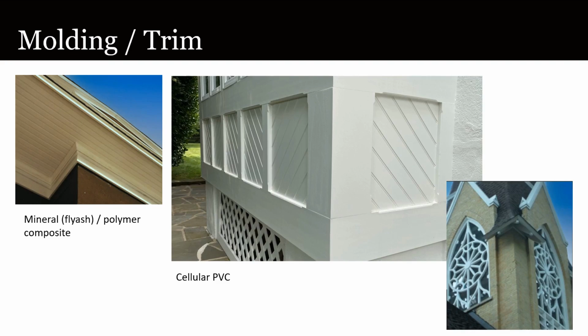For example, moisture will have no effect on the movement of a piece of cellular PVC. It will expand and contract with temperature change, though, but for a short section, that movement will typically be much less than the movement an equal-sized piece of wood will have across its grain as it wets and dries. By contrast, a 16-foot long piece of wood will not change in length noticeably from either heat or moisture, whereas an equivalent length of cellular PVC will change dimension enough with normal solar heat gain to require accommodation at the ends for the change or fasteners to resist it.